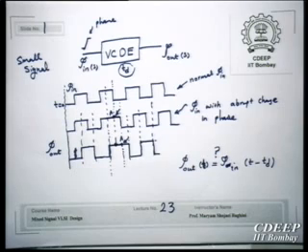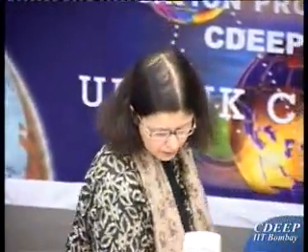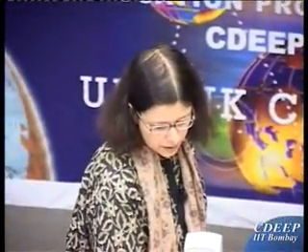This is a signal, right? But we are looking at the phase of the signal. If you change the phase of the signal at time equal to 0, when do you see this change at the output? Same delay. Same delay, ignoring any other thing. It's just a delay element with a delay of T. Then what does it mean? If I can write this, then in Laplace transform, phi out s will be e to the power minus sT into phi in s.